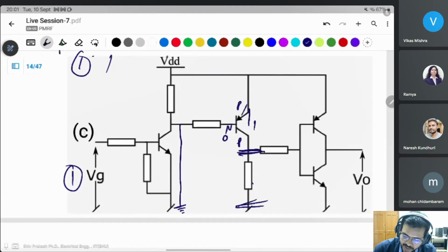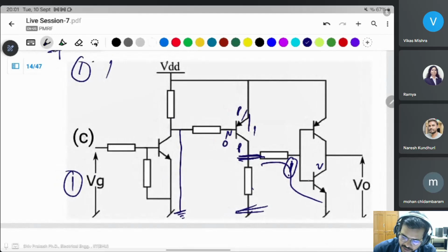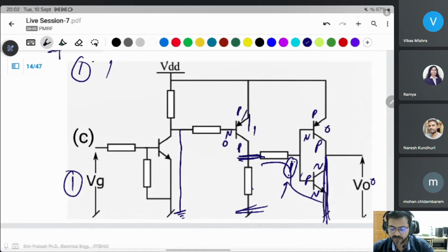This voltage is applied to the VBE. It means there are some voltages here. There is a high voltage, then this is the NPN transistor, and this is the PNP transistor. For the NPN transistor, if the base voltage is high, then this will be forward biased, it will be working. And this is working, that means this will be short circuited, the output voltage is 0. Here high, then this will be 0. This is the connector here, and this will be the 0 voltage because it will connect to the ground. If given 1, it will be 0.